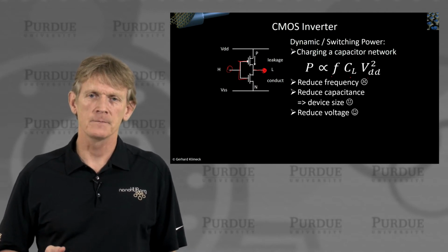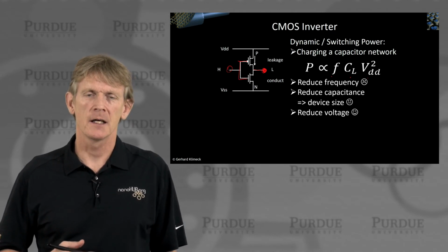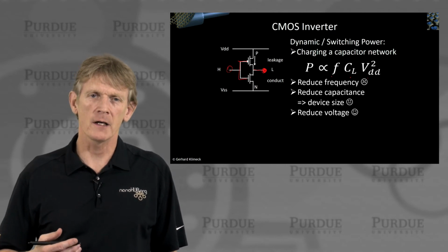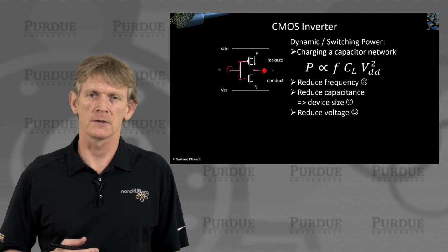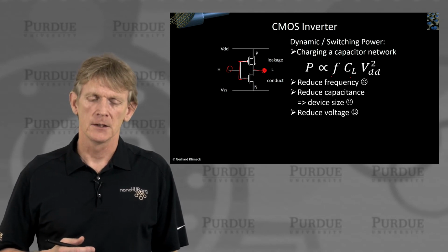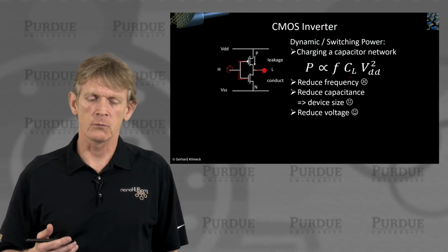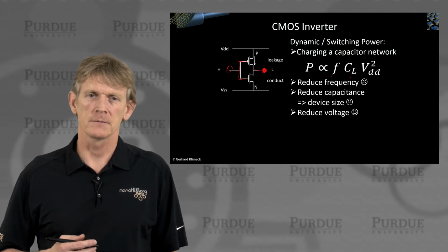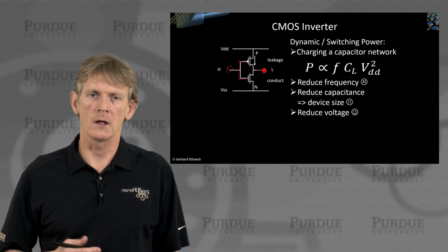And as I mentioned, the beautiful thing about CMOS technology was that it was only consuming power when it was switching. There is, however, another component in this power loss in the circuitry, which is the leakage. So regardless of whether it is switching or not, one of the two transistors will be leaking some current, and I'll show that in the next slide. And that current will ultimately lead to some loss.